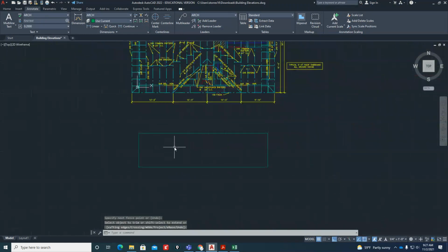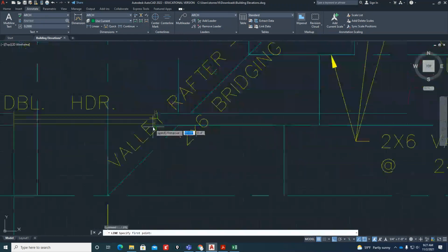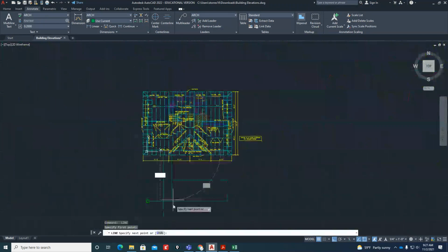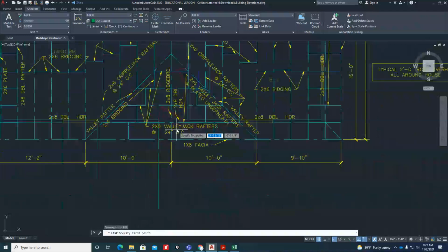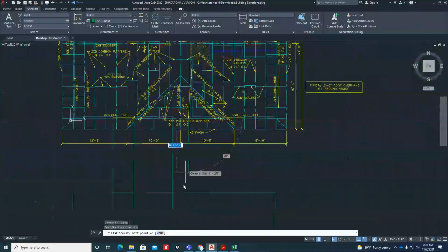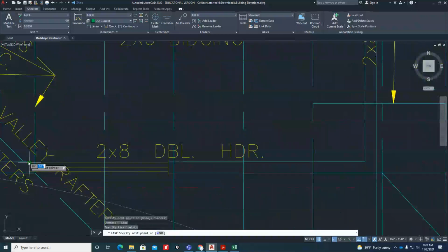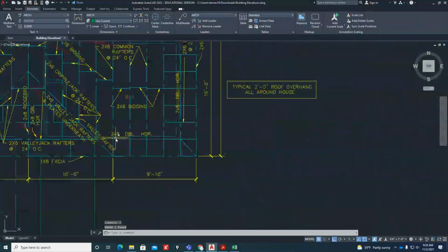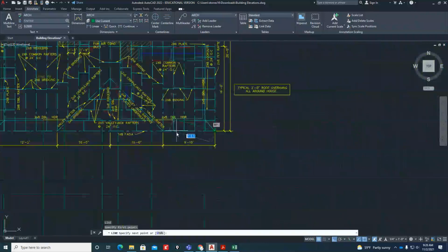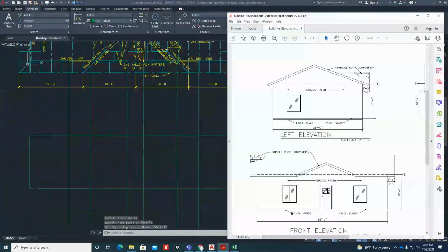And then from there, I can start projecting the location of the windows. The windows are simply going to come from here down this way, and then from the edge of the window down this way. And notice again, it's all being done by projection. Same thing with the door opening coming down to here, and the other window that we have in the front bedroom right over here, which is the edge of the window. Coming down here, of course, so I drew that line, not really needed. And then from this edge right down to here. Okay. So then the other question is, what's the height of the window?